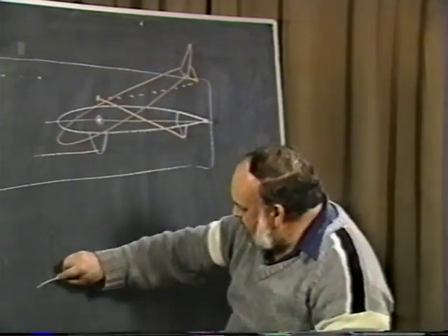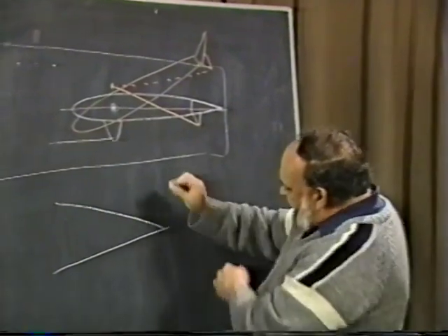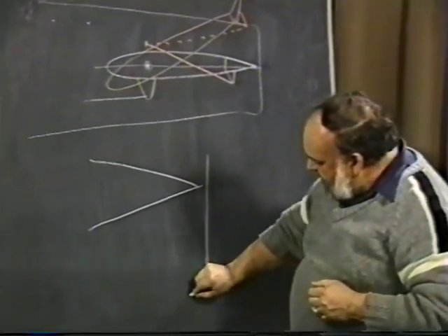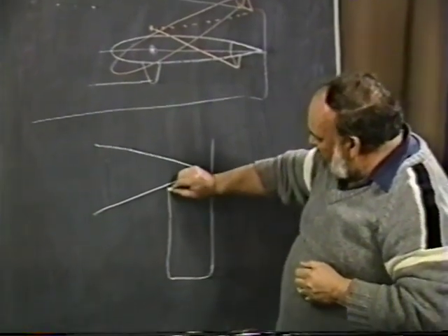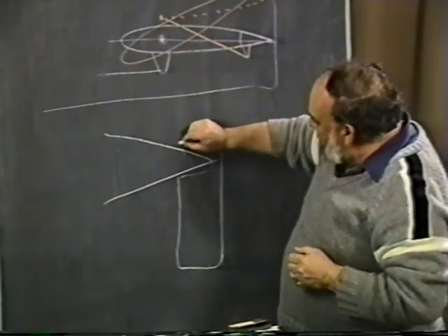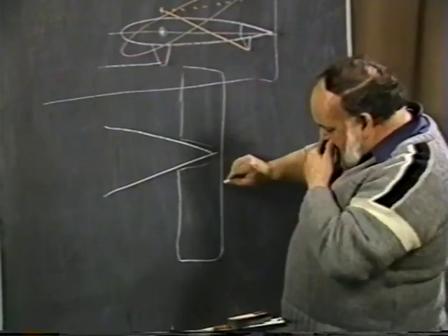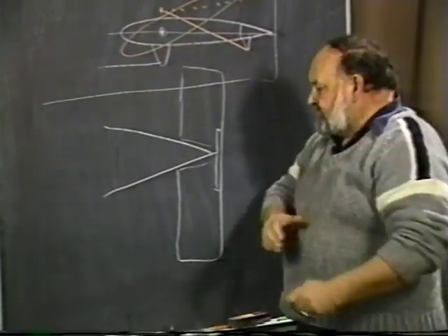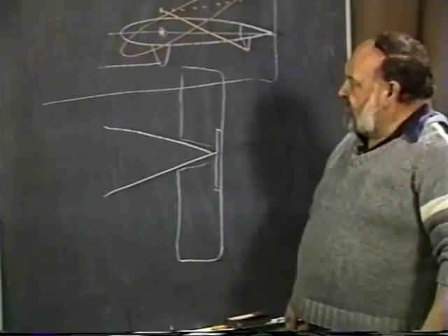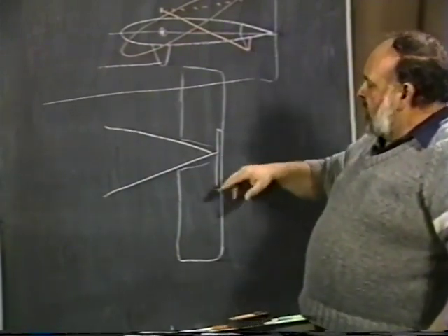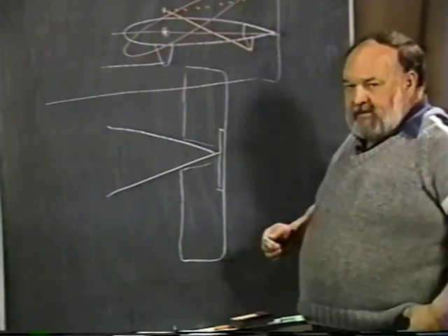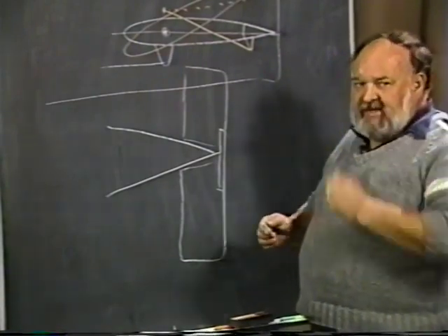From a top view, let's assume this is the fuselage. And, well, let's take even the case of the Bede 4, where we had essentially a rectangular planform for the horizontal tail back there. We put the servo tab in this region in here. Now, everything's perfectly fine. Everything's balanced real nice. It pivots on the quarter chord, the servo tab, anti-servo tab that is, goes ahead and gives you the stick forces you want and everything else. But there's a couple things you have to be concerned about.